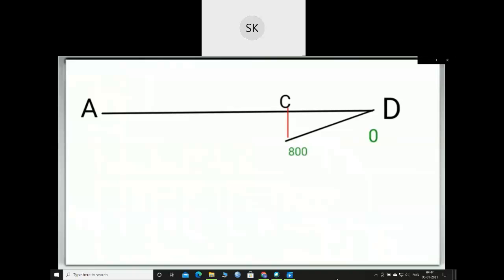Now the bending moment calculated at point B is equal to minus 2000 Newton meter. So we will mark this point as 2000 Newton meter to some scale below the baseline, and join these 2 points by a straight line, since this span BC follows a straight line rule.